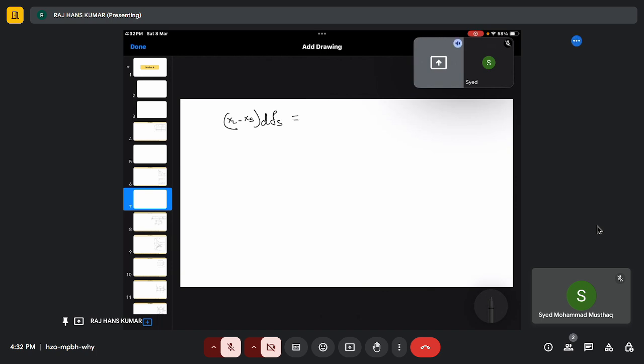That will be equal to the concentration in liquid that has been formed into solid. That will be dxl. This is the change in the liquid because of the solidification. Some part of solute is being rejected into the liquid, so that will be equal to 1 minus Fs, that will be Fl. So we are writing 1 minus Fs. Now, this is our differential equation.